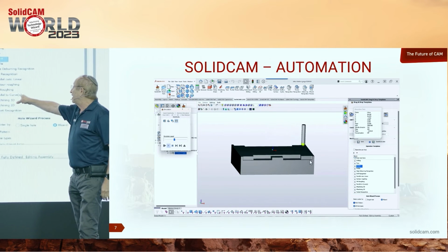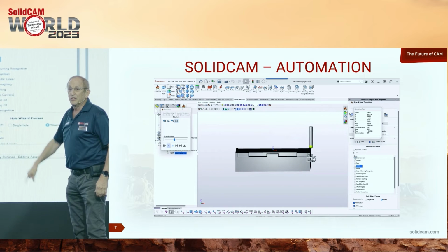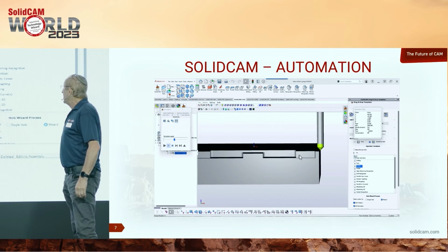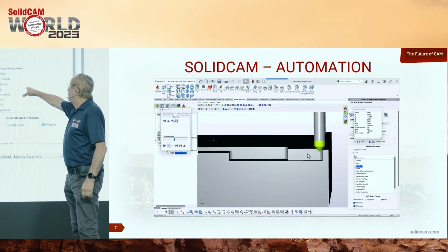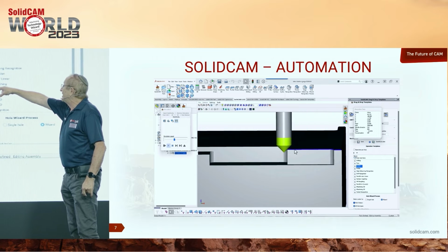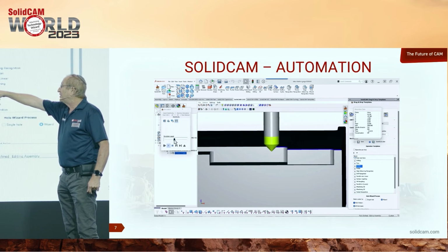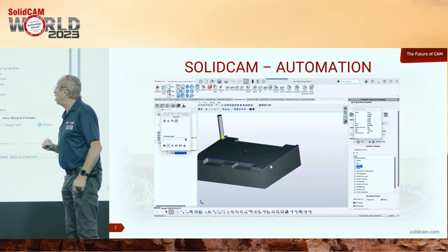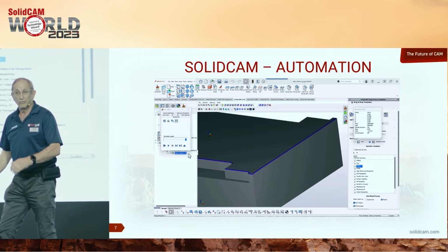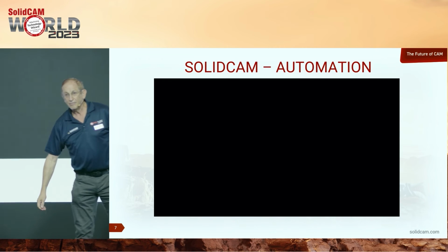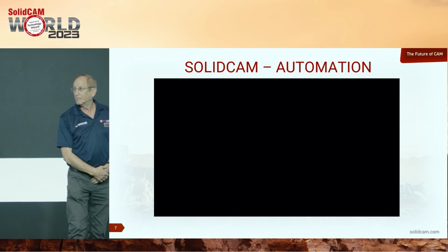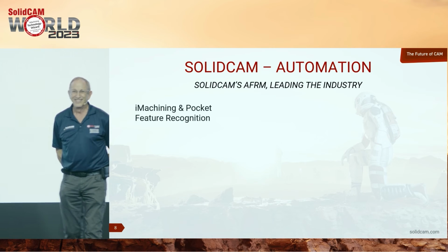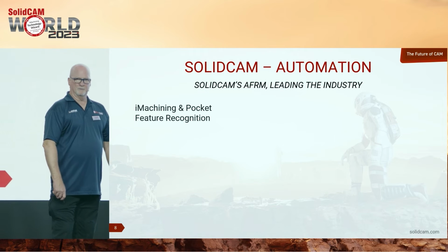You can see over here inside our simulation of Solid Verify, as it's going further and further down along the part, as it gets towards the actual boss itself, you'll see that it jumps up and continues on the entire part. Gives us a nice consistent chamfer all the way through there, even though it was doing the avoidance. It's very cool. Thank you. Good job, Sidney.